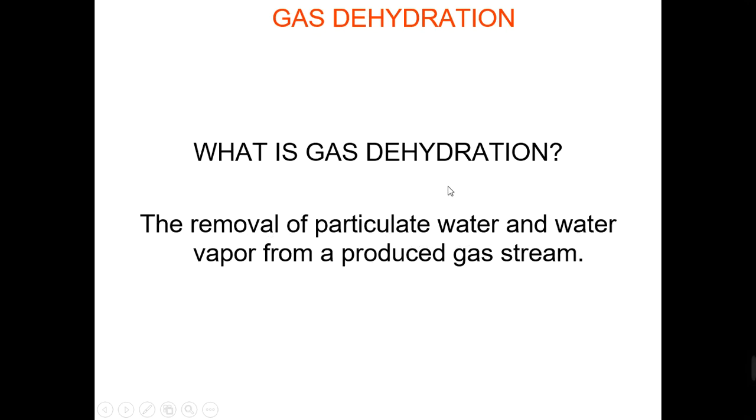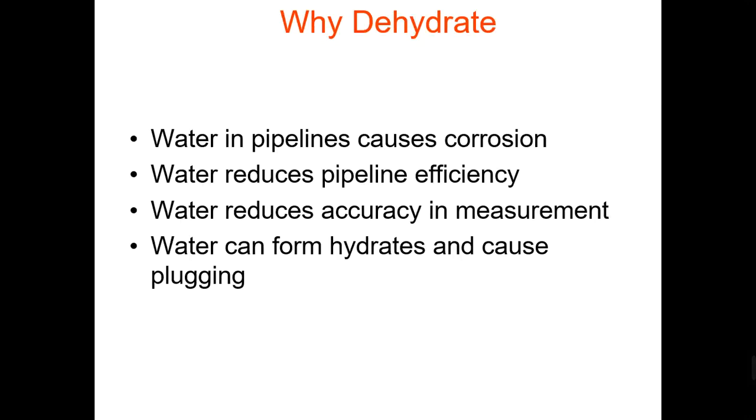Now, this is a very important step because this water vapor inside the gas, when it flows, can cause lots of problems for us. Two of them are major problems. One is hydrates formation, another one is corrosion. If corrosion happens, it can lead to leakages, and then consequence after consequence. The same for hydrates: if hydrates happen, they can malfunction many equipments and reduce the capacity. So many problems can happen because of this water.